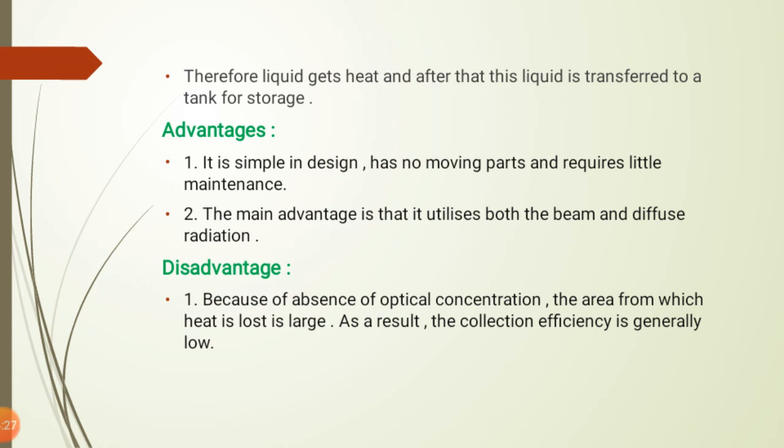But it also has a disadvantage, and there is only one: because of the absence of optical concentration, the area from which heat is lost is large. As a result, collection efficiency is generally low. There is a loss of heat, by convective or radiative heat losses, in large quantity, due to the absence of optical concentration.